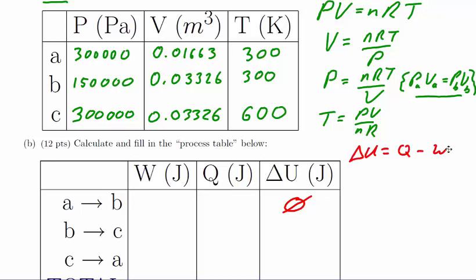The first law of thermodynamics, delta U equals Q minus W, will be used to calculate the third when we have any of the 2. As you can see, when delta U is equal to 0, Q is equal to W, and therefore we will be using a single formula. I remember it most easily for W, that the W during a constant temperature process is nRT natural log of V2 over V1.